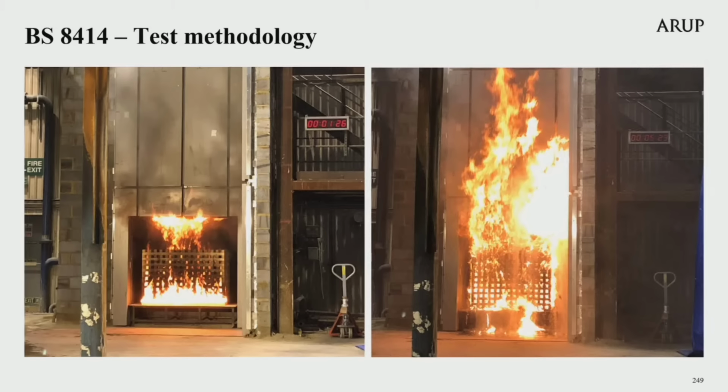5 minutes before the crib is ignited, the thermocouples and audio-visual equipment begin taking measurements. The crib is ignited. Temperatures and visual recordings are made from 5 minutes before ignition until 60 minutes after ignition. The crib is allowed to burn for 30 minutes, at which point it is extinguished.